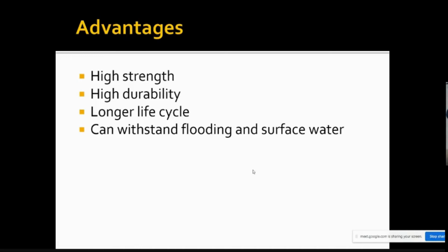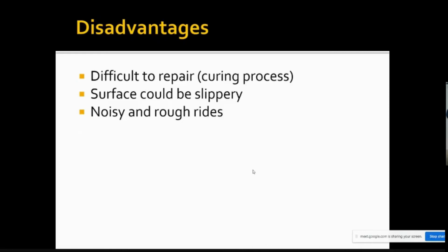Advantages: high strength, strong, high durability, it lasts more than 10 to 15 years, even more than that. Longer life cycle, can withstand flooding and surface water. Difficult to repair because it is concrete. So if it breaks or cracks, then you have to break that part again and you have to grout. So there is a lot more work for you to do.